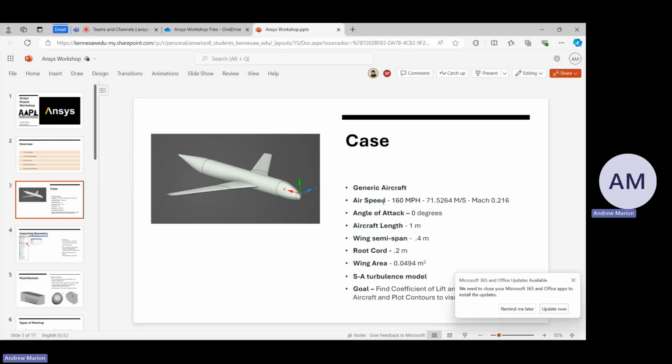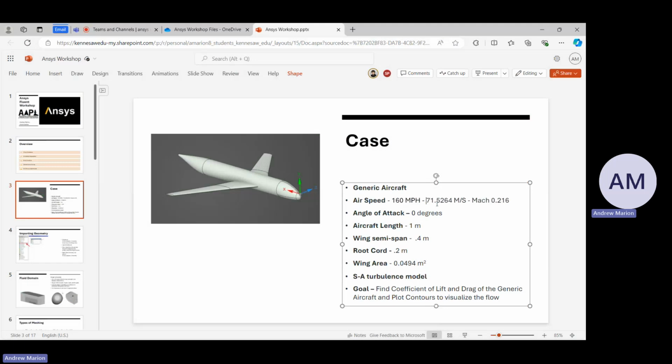So if you want to do the wing incidence, then you could rotate the wings up a couple of degrees and leave the fuselage. Wing incidence is when you have the wing at a couple of degrees high or low. It's basically installing the wing onto the aircraft already at an angle of attack. So even though the aircraft itself is flat, the wings are already angled up. That's called the wing incidence.